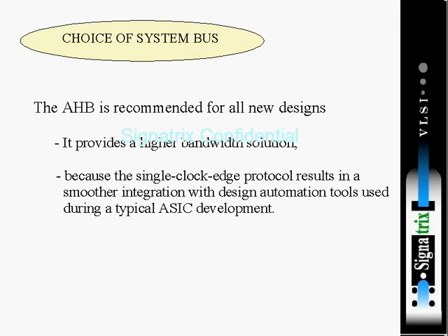If a particular event occurs, then only it will evaluate the circuit expression which is related to that event. Okay, but in the case of cycle based simulation, we are going to have one clock cycle. It will definitely be a very high speed clock cycle. Okay, so in every clock edge it is going to evaluate each and every part of your circuit, right?